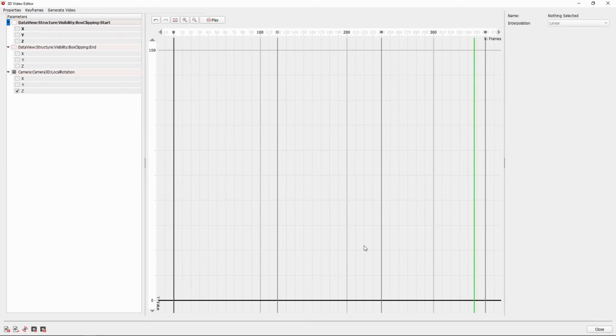We now have to add the control point for the parameter on the keyframes ourselves. Since we want to do a full rotation on the z-axis over the whole time, we only need 2 control points. One at the beginning with the value of 0 and one at the end with the value of 359, which gives us a nice seamless rotation that is great for looping.